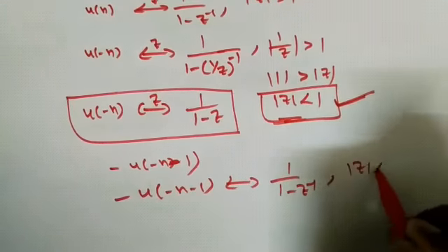That is about this. Now we will solve some problems on the z transform using the properties. Just now we have seen all the properties, and using those properties we will try to solve some problems. To solve this one, we first need to expand it using Euler's relation. So this will become e power j omega naught n plus e power minus j omega naught n by 2 into u of n.